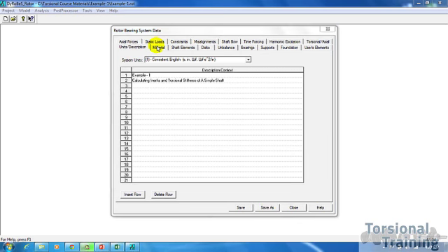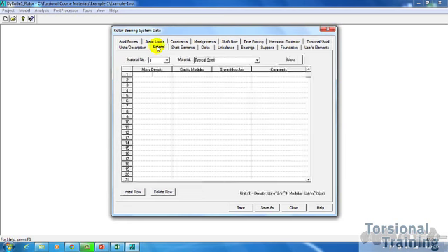The next step is to select the material that we'll be using for our particular shaft. So click on the material tab, and you have an option of selecting, looks like 201 materials in this particular model. Now typically some of the more complex models that I've built, I may have at most 8 or 10 materials. For this particular example, let's just select material 1, which will be material number 1, and let's pick typical steel, and go ahead and click select.